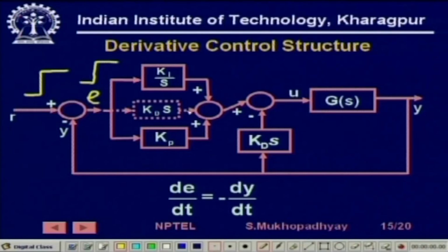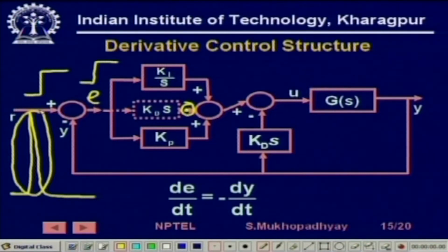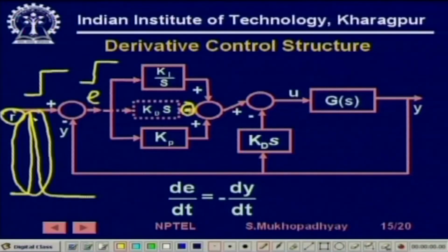So, then what will happen to the derivative output here? At this time, it is going to rise very much and then fall to 0. So, you are going to give a shocking input to the plant if you put the derivative here. Now the question is, how can I avoid such shocks, but if R is constant, and Y changes due to various other factors like disturbances, I need to keep the derivative control.